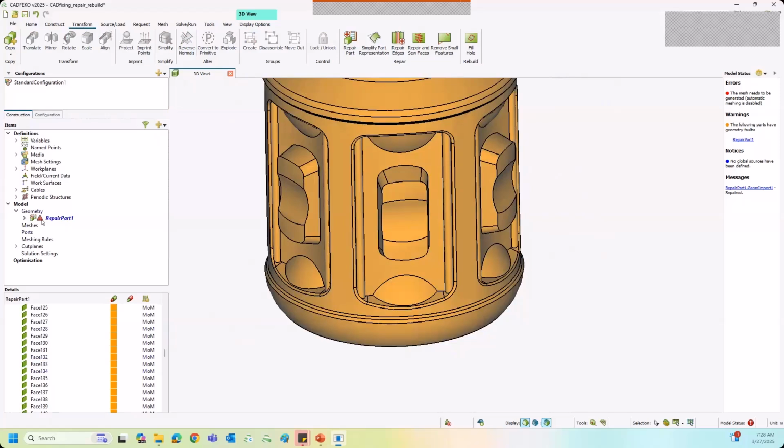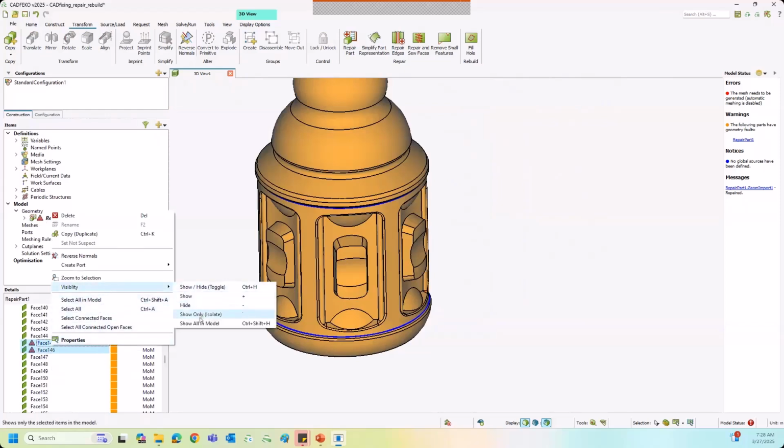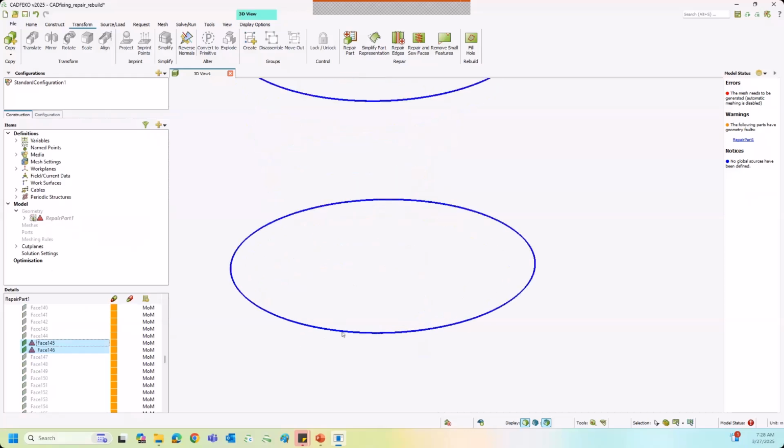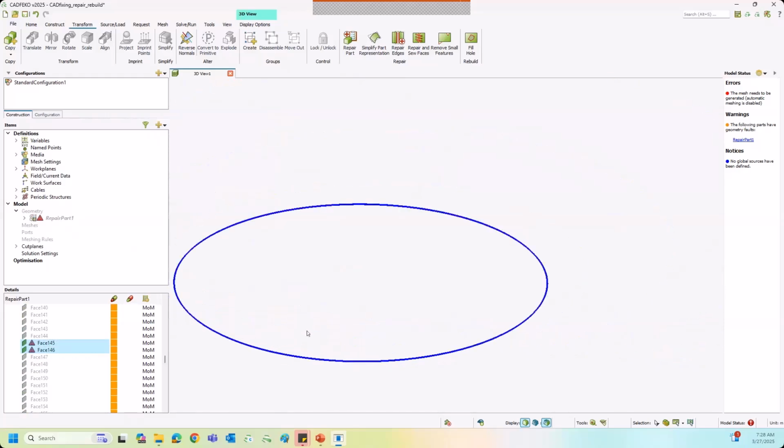But it looks like there are still some more geometry faults. So if I scroll down further, I see these two more parts. If I select just these two, right click and isolate them, I can see that these are very tiny slivers within the model. These types of tiny slivers are never good for any CAD. When you try to mesh including these tiny slivers, that can lead to a highly inhomogeneous mesh, with extremely tiny dense elements on these particular parts, which is not good for the solver.